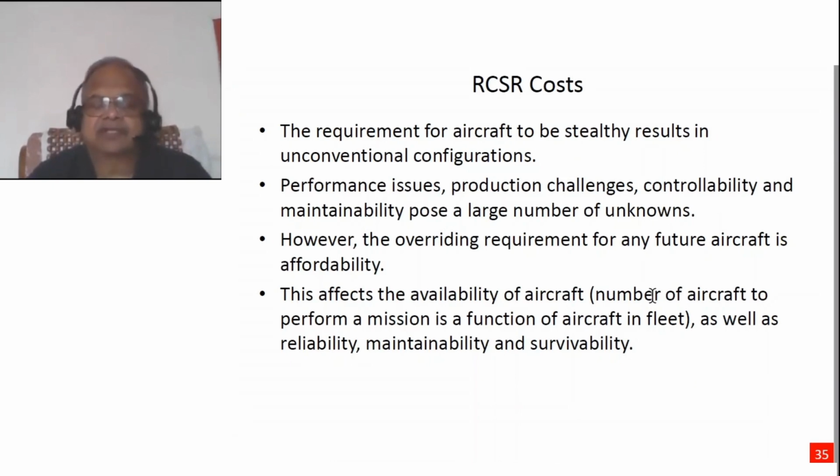For example, this kind of coating is effective only if the thickness is one-fourth the wavelength of the incoming radar. Now, if the radar frequency is changing, obviously one size cannot fit every aircraft, so you need to keep changing that.